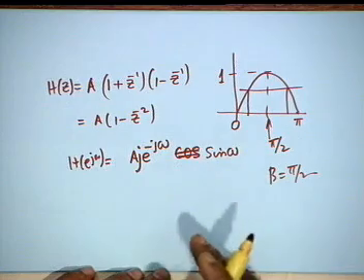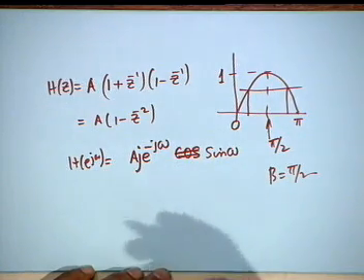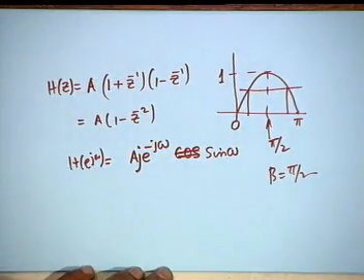Suppose I wanted a band stop, then what should I do? High pass plus low pass, plus in the sense of parallel. All pass minus band pass would be a band stop. Yes, we will use this. But tell me the simplest.